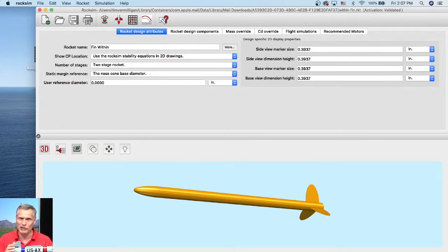You can get really lightweight, 6-pound density balsa wood, or else you can get like 12 to 14 pound really heavy balsa wood, and that's going to make a difference in strength as well.